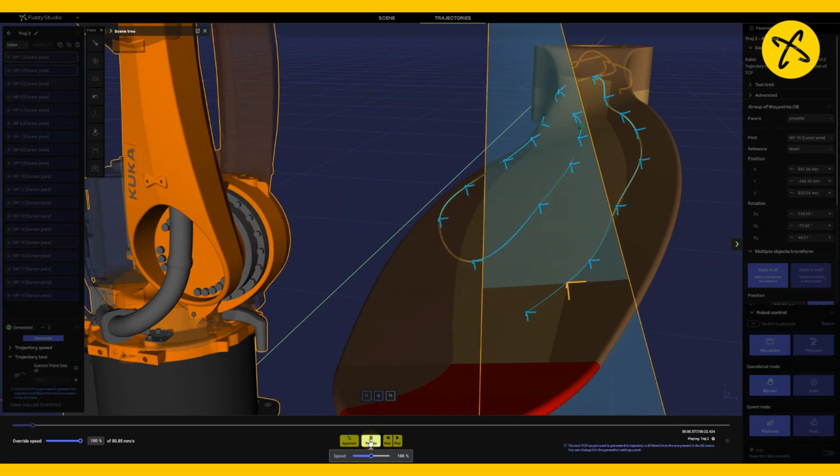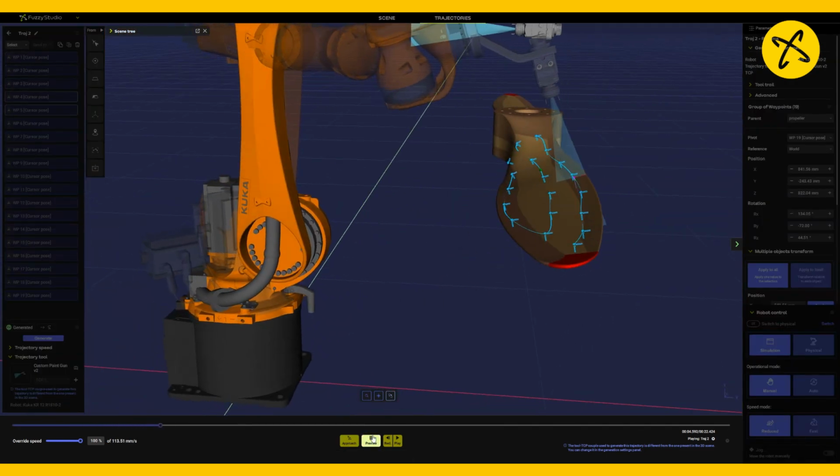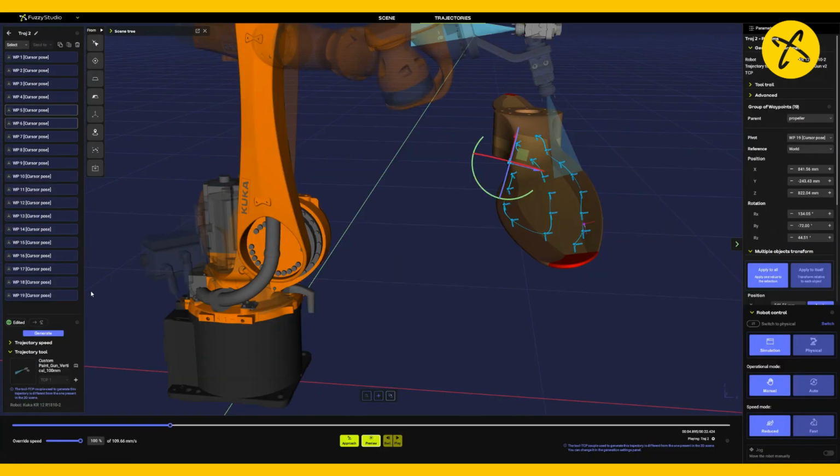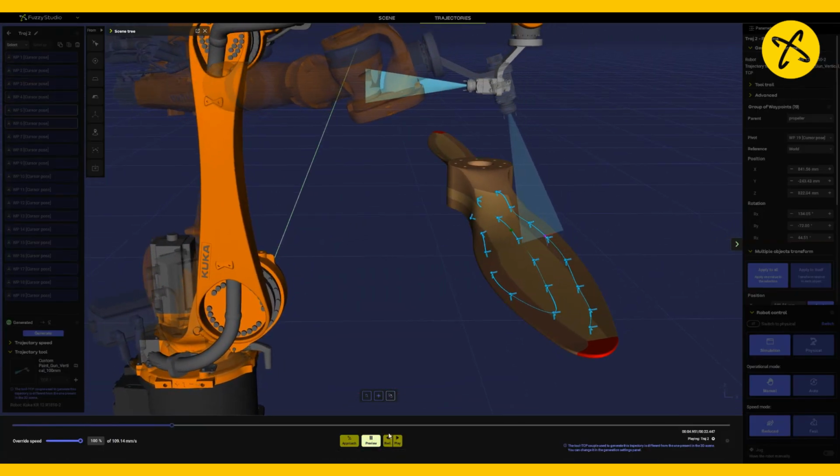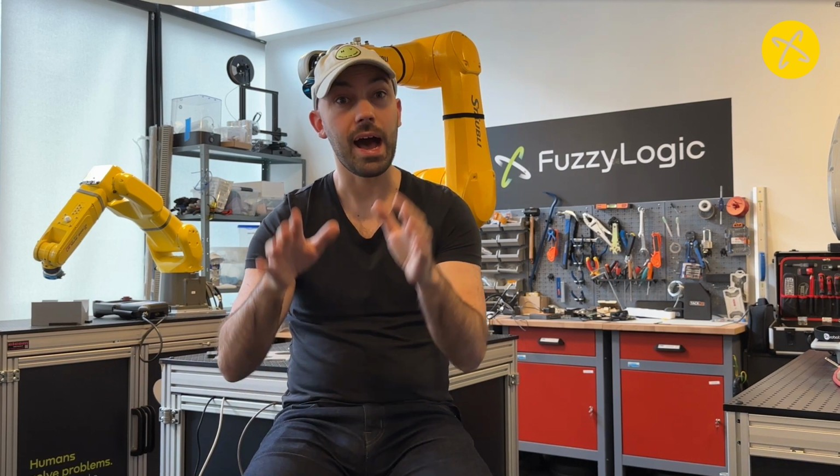Even if the selected tool doesn't appear visually, its TCP is represented. You can therefore generate as many toolpaths as possible and associate them with as many TCPs as desired. Ideal for applications where tooling changes occur on similar trajectories.